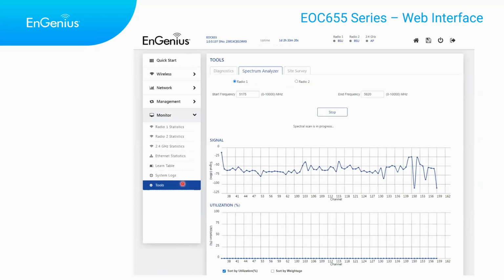So the spectrum analyzer that I was mentioning can be run directly from the system as well. Here they're running the spectrum analysis on the 5 GHz radio, so radio 1, and then utilization on the bottom. Here you can see where the noise is, so that when you deploy, if you're going to use, let's say, manual channeling, you can set it based on here. Based on this, let's say channel 150 has the least noise. But of course, you can also do auto channel or dynamic channel selection and just let the radios do the system configuration for you.